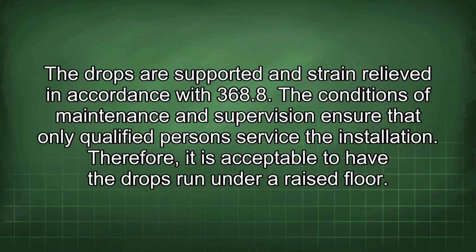The SO cord is terminated in a receptacle and all of the equipment is plug connected. The drops are supported and strain relieved in accordance with 368.8. The conditions of maintenance and supervision ensure that only qualified persons service the installation. Therefore, it is acceptable to have the drops run under a raised floor.